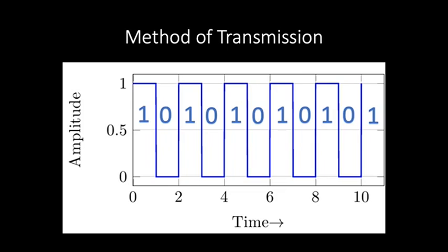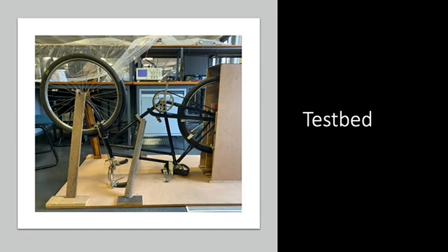For this project, an on-off keying modulation scheme was used to transmit a light signal. This is one method of how binary data can be encoded into light signals. By using OOK modulation, any alterations in the signal frequency spectrum would be as a direct result from the Doppler effect, and thus can be easily identified and addressed. A testbed is required in order to test the effects of Doppler shift on the communication system, by putting the transmitter and receiver circuits in motion relative to one another.